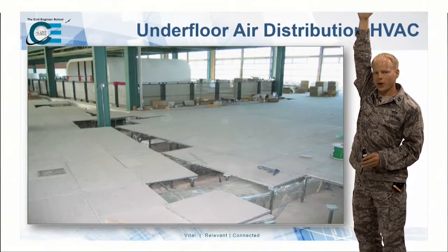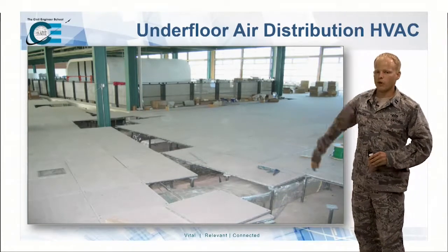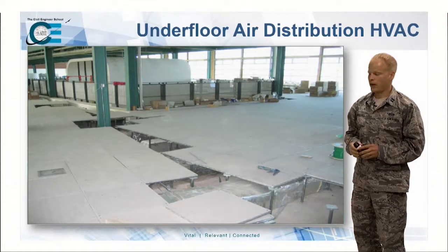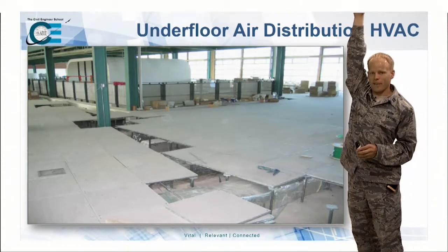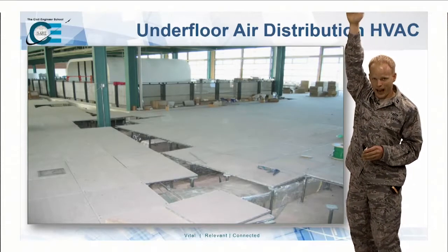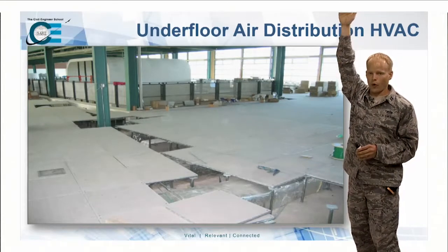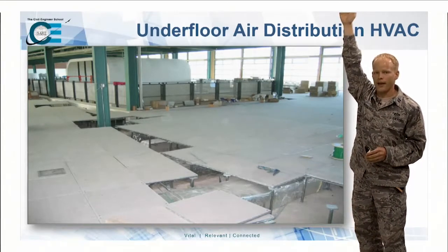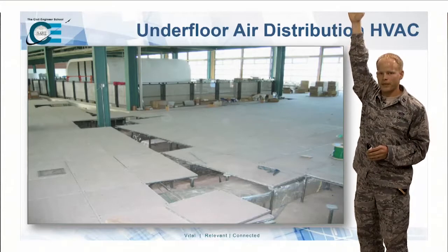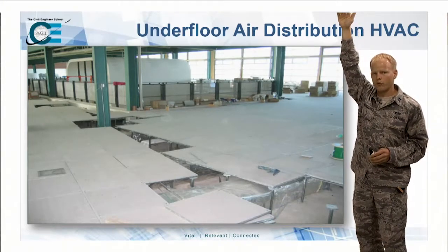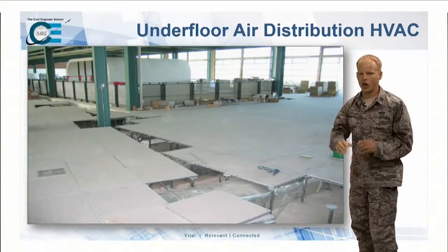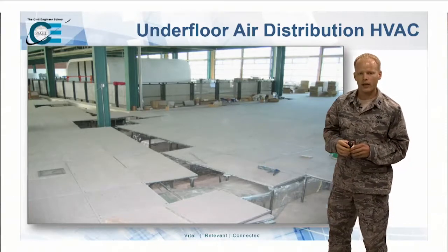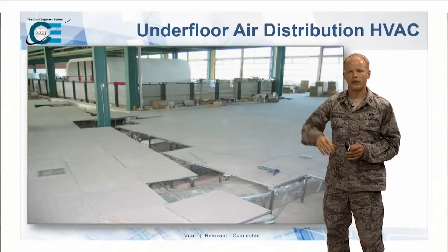I think it's 8 foot. Because most people are not 8 foot tall, we don't need to cool this area up here. Nobody's running around saying, I need to breathe up there, or I am sweating because it's really hot up here. So if we can cool up to 8 foot, we will now reduce our zone, especially in large office buildings where you may possibly have higher ceilings.